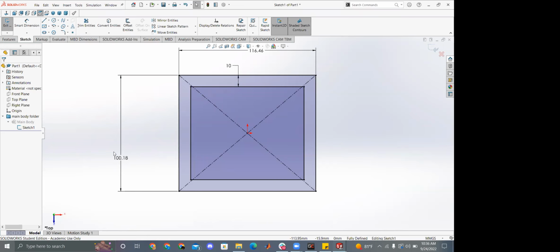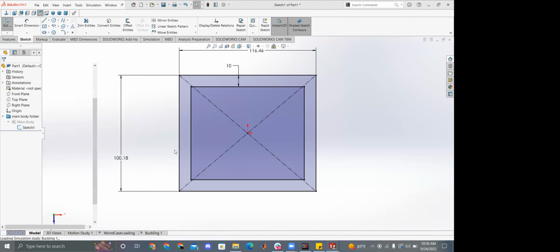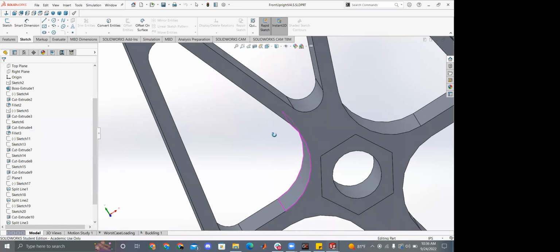If you have a very small area with the same force, it's going to have a lot more stress. And a corner goes to basically nothing in terms of area. So it's going to have a very high stress. The way we combat that is with something called a fillet. I can pull up my shameful old model. You can see these corners.